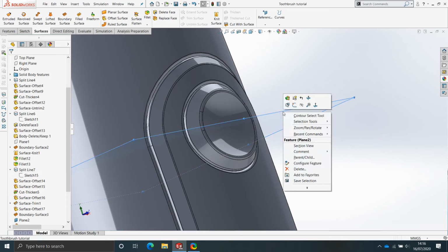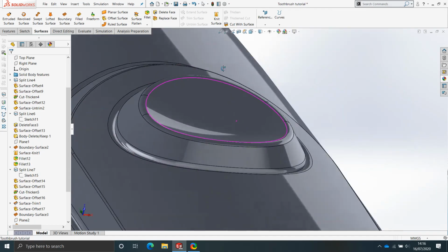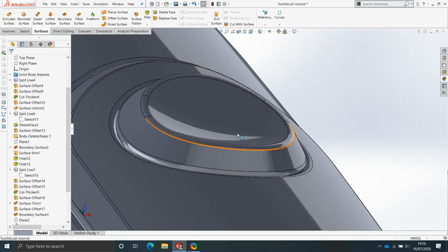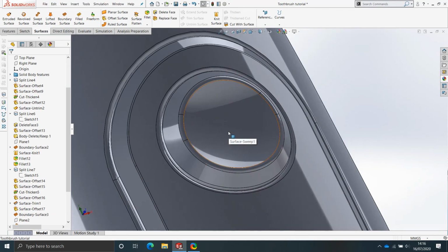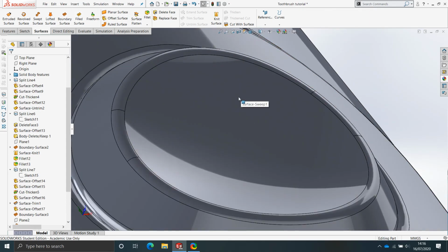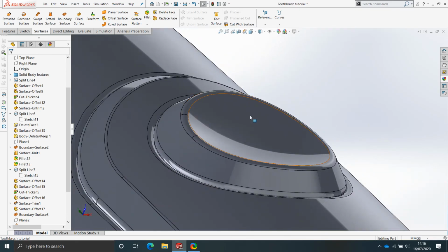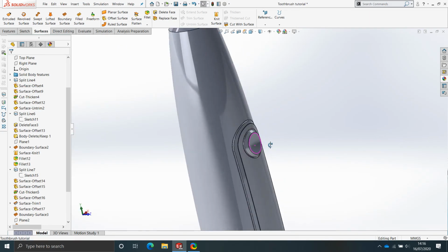For those of you looking to push a little bit further, I'm not going to go any deeper today, but if you wanted to shape this even more and you couldn't really achieve it with a surface sweep, I'd start to look at surface boundary in a little bit more depth. This can be great, and the only reason I didn't use surface boundary today is because we would have needed to create more sketch geometry, because when you're creating a boundary, ideally you want 4 sides, not 2 or 3, otherwise it tends to create pinch points. But yeah, go and have a play, explore with the surface tools, and that's all for today.